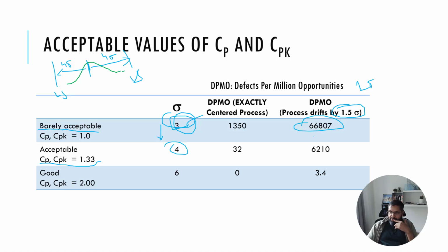So it's not touching the sides. There's a 1 sigma gap here, and a sigma worth of gap here, because this is 3 sigma and this is 3 sigma. Okay, so 6 sigma width is inside your 2 specs, and you have 1 sigma extra on each side, which is why this is called 4 sigma. So that's 4 sigma level of quality.